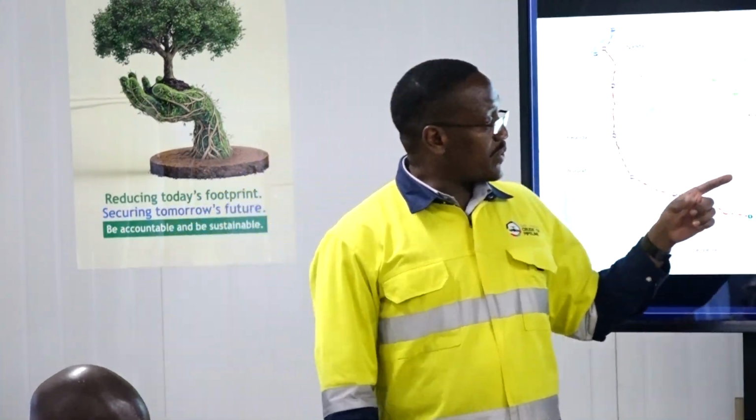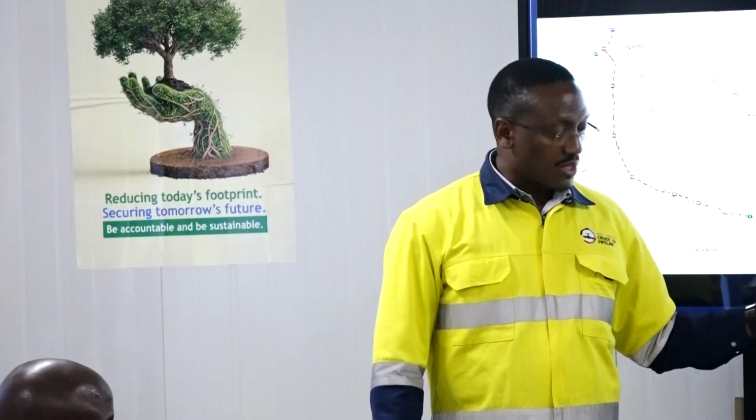But when we are doing the hydro testing, we had to get sections, probably a 60-kilometer section, and hydro test. After you hydro test this section of several pipes joined together, you're sure that each of those welds' integrity is okay. But what happens between sections? Between sections, when we join the 2 hydro test sections, we cannot again do the hydro testing.